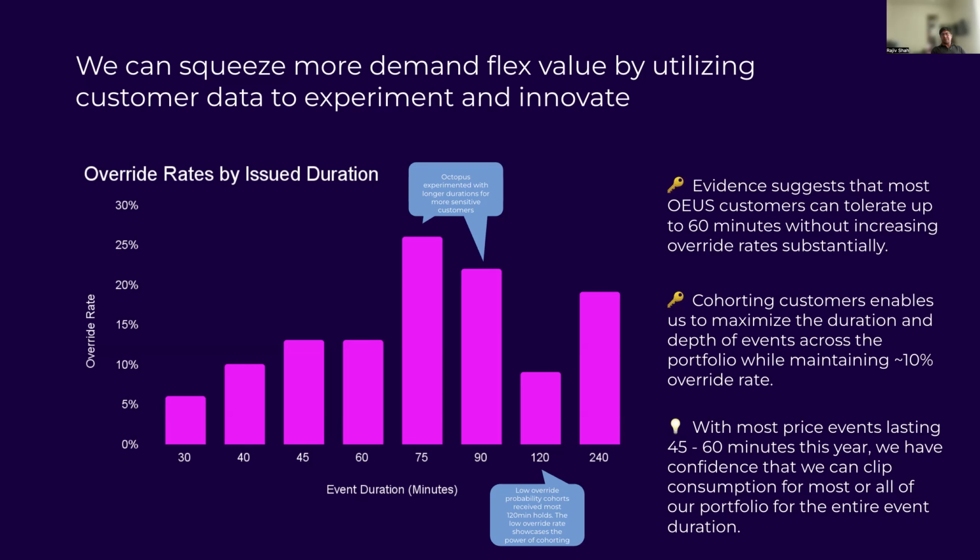We've actually iterated on this further in that we know when the HVAC system is re-engaging for our customers after we've set a thermostat hold, perhaps increasing their temperature by about 3 degrees, which is what we've seen most customers are comfortable with in terms of a fluctuation from their thermostat setting. And so that actually has given us a proxy for assessing what the thermal envelope is for our customer and associating the durational capability with that thermal envelope.